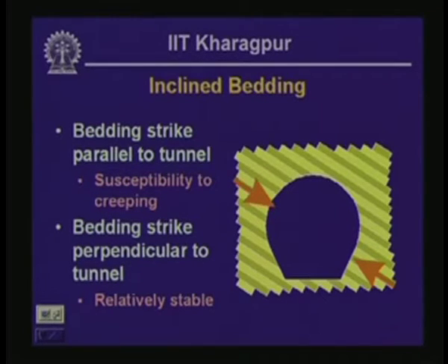What is going to happen as soon as the opening is made, because of the direction of the major principal stress, the rock mass within bedding planes is going to try to squeeze into the tunnel.